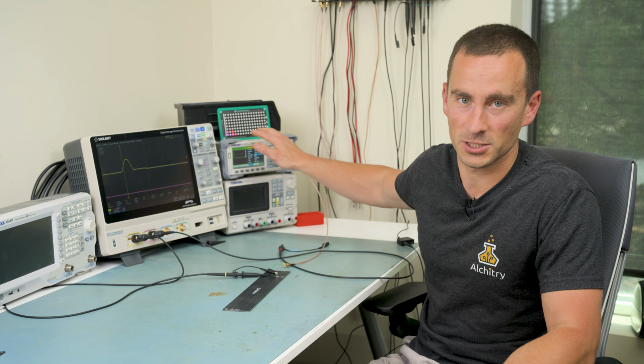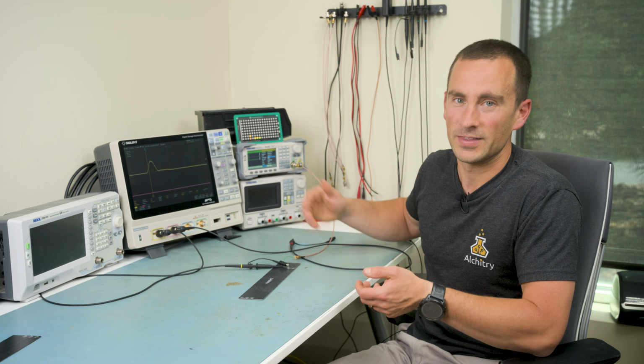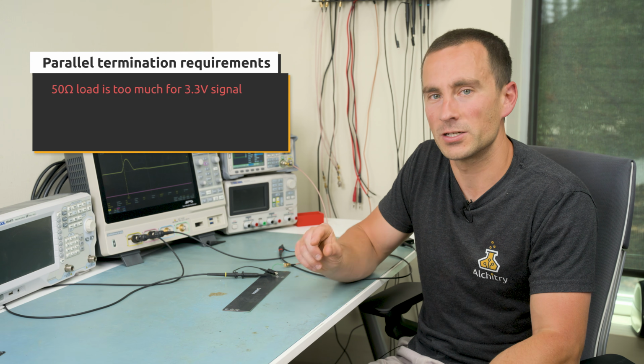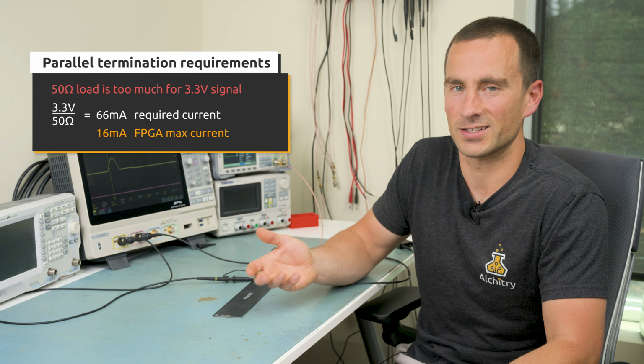It absorbs the reflection. This demo board was originally designed for an FPGA to go on it and create the signals. However, as you notice, I've been using the signal generator so far to drive the lines. That's because an FPGA can't really drive a 50 ohm line with parallel termination. A 50 ohm load is just too much for a 3.3 volt signal. It would require 66 milliamps of current, and the FPGA pins max out at about 16 milliamps.